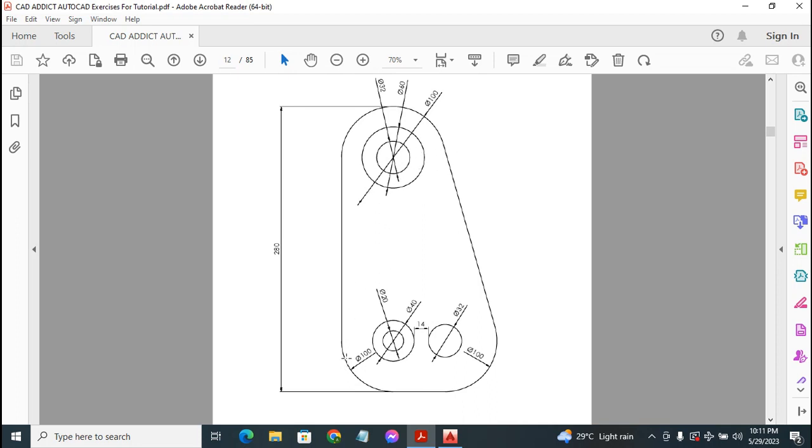To do that, we have to produce a vertical construction line using the tangent point on this base circle. Then right from there we can offset from this vertical construction line at a distance. If the entire diameter of the circle is 100 millimeters, that means the radius is 50 millimeters. So we're offsetting the vertical and horizontal construction lines at a distance of 50 millimeters respectively, in order to locate the center point of this upper circle. So let's do that. Back to CAD.